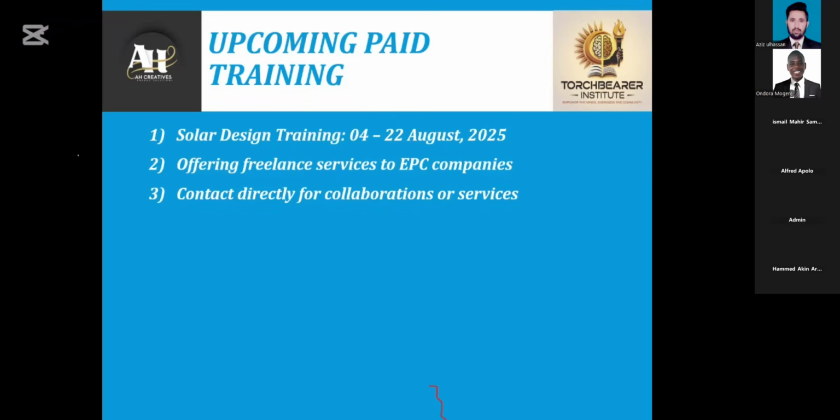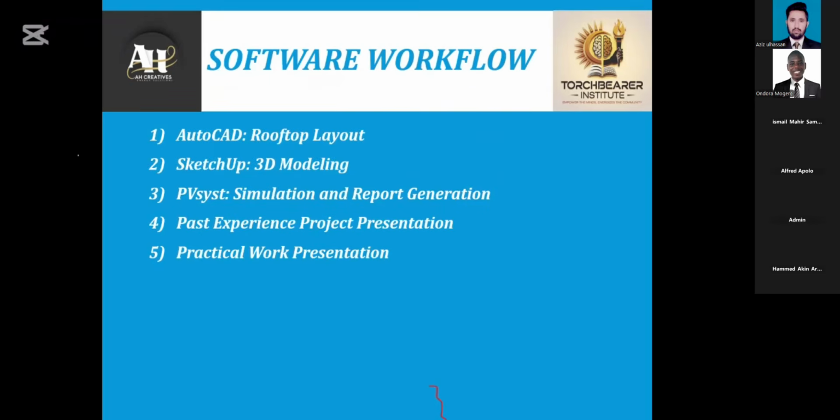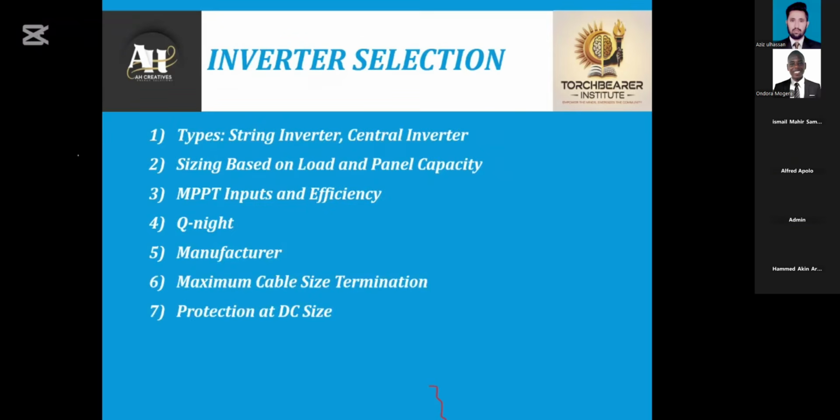The new manufacturers like Huawei and Sungrow, with their updated technology, allow the inverter to generate the VAR. You are all engineers, and you know about VAR, reactive power and active power. We have to provide the VAR compensation at the grid station where we terminate our solar systems. So we have to compensate the VAR requirement from the grid.